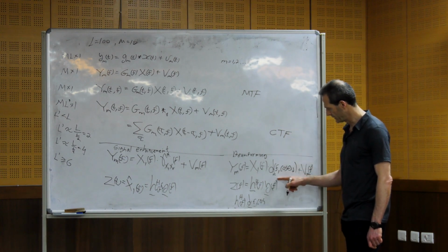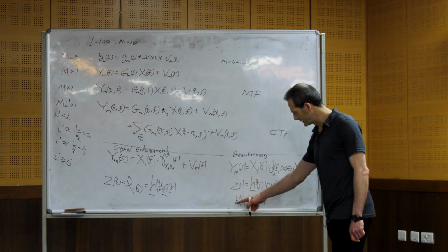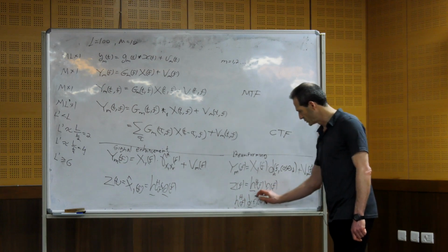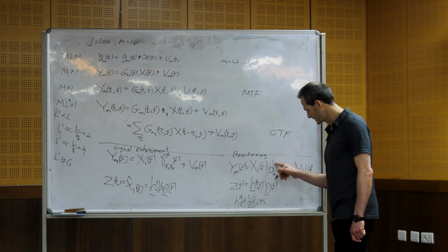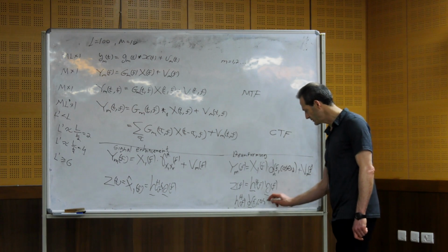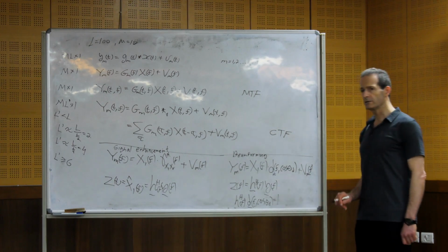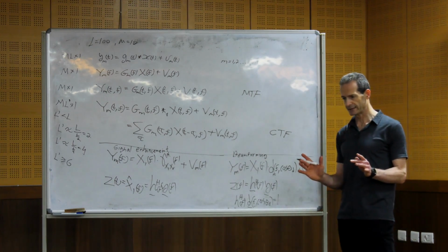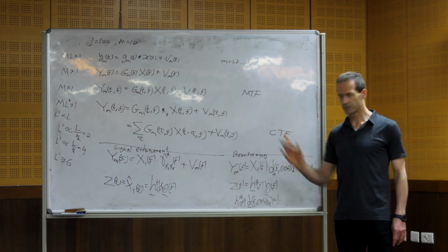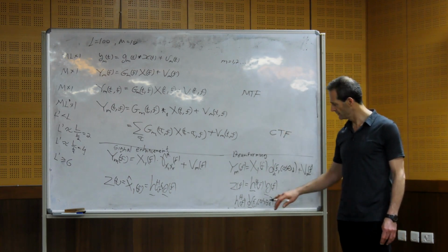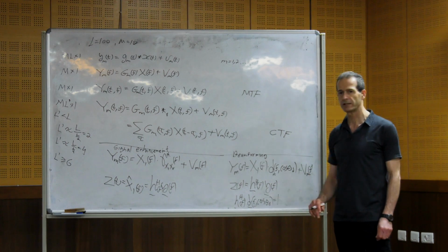So if we apply the beamformer to the steering vector, which contains all the m components, theta d, it is required that it will be 1, so we have a distortionless response of the array towards a certain direction, theta d.